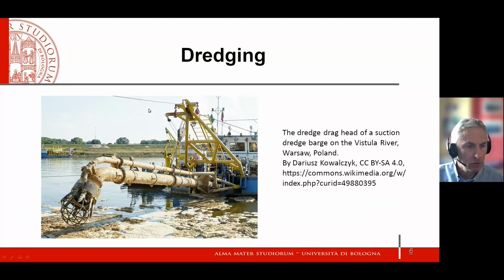This is an example of a dredger, called a dredge drag, and it makes dredging by suction. So there is aspiration of water close to the presence of the sediments, and therefore, while taking water into this dredge drag, you also bring sediments suspended in the water.